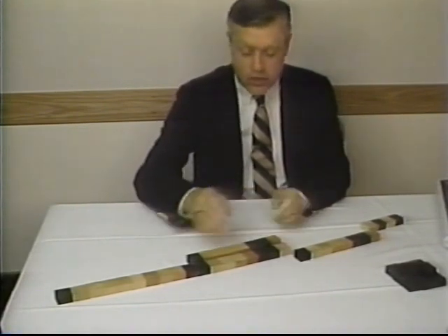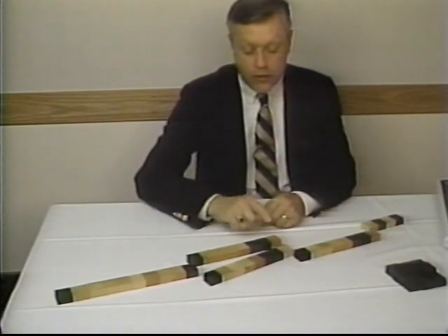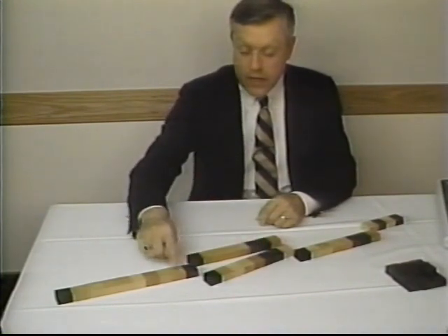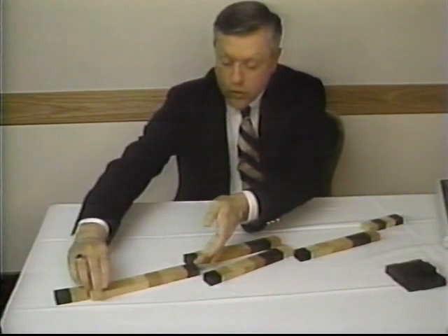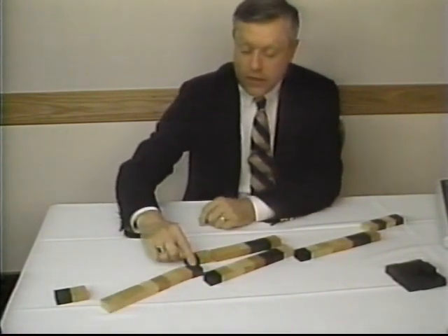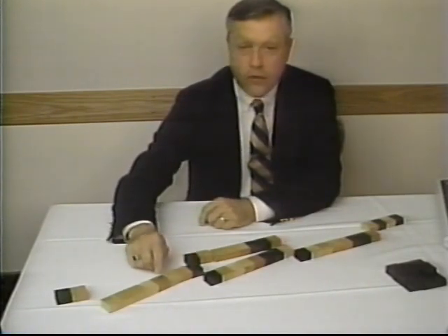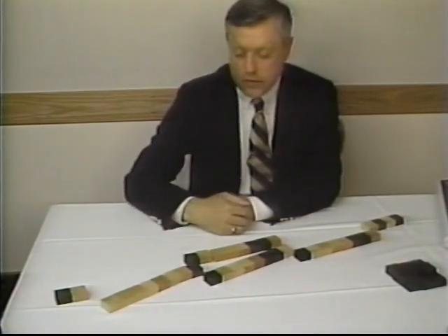At that time, it should see the second sync character. At that point, it says, I've seen 2 sync characters in a row. I have synchronization. If I count off every 8 bits afterward, what I will see is an individual character. And if you look at this character here, you'll see that in the ASCII chart, a 1 followed by 7 zeros is the code for the ASCII character start of header. So that's the beginning of our message.